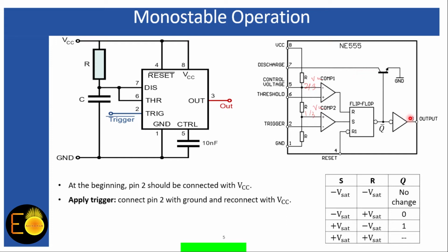That's why this operation is called monostable, because for the time the capacitor is charging from 0 to 2/3 of the VCC, the output can stay in its quasi-stable state, and during that time if you connect a buzzer at its output, you can get a constant ring.